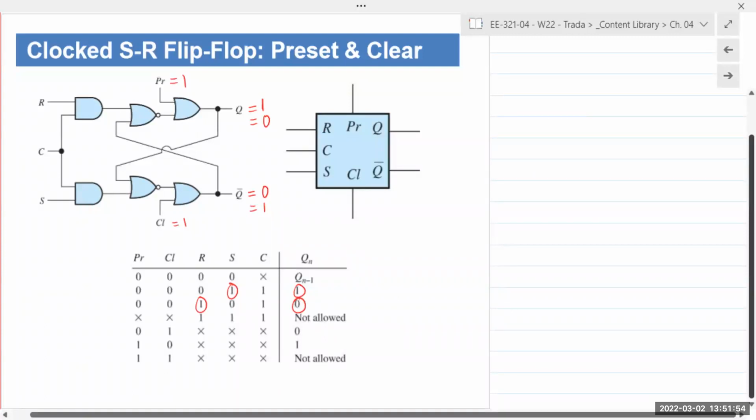We're only talking about 1 bit, but modern computers are 64 bits. So each bit is like 1 line, and all of them put together are known as a bus. Previously we had 16-bit processors with a 16-bit bus, 32-bit processors with a 32-bit bus, and 64-bit processors with a 64-bit bus. Everything's running in parallel at the same time, so 64 lines. If you were doing a simple 64-bit circuit, you would have 64 of these flip-flops, one for each bit.